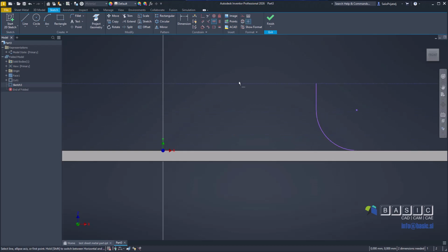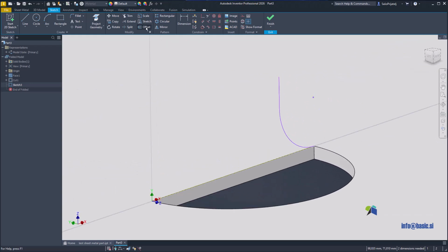so we have full 90 degrees here. Then I will create an offset. Right click and deselect loop select and just select those two. Right click, continue, and create some offset here, and then finish the loop with two straight lines here and here. Then create a dimension and this should be equal to thickness of the part. You can just click this arrow and click list user parameters and select here thickness. So we will use this to revolve around.